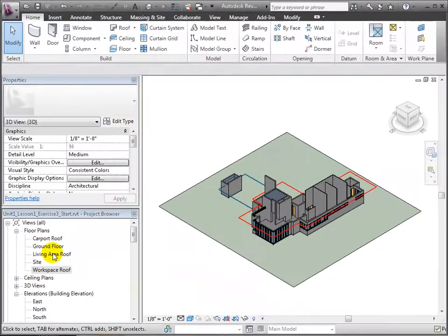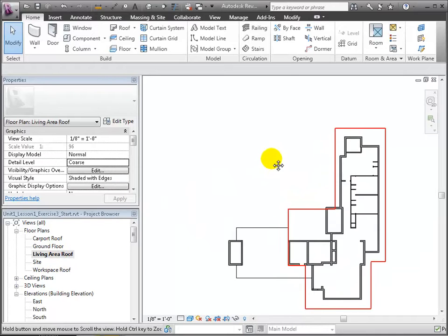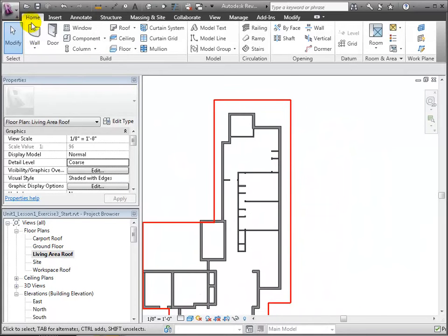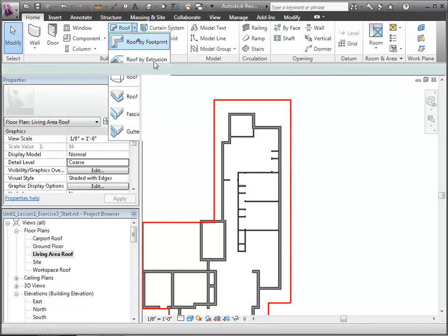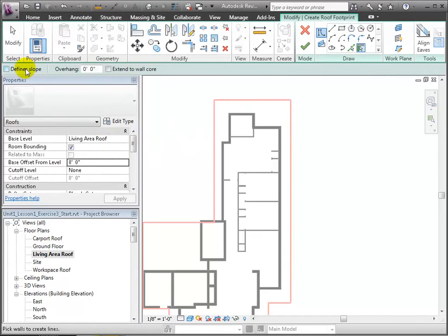Now let's try doing the same, except to make a sloped roof. We will place a partial roof over this north wing of the building. We've already set this example up with model lines at the precise locations of the roof boundaries to make it very easy. We'll leave the slope-defining property checked for the 3 boundary lines here that coincide with the building's exterior walls. Let's use the Pick Lines tool and follow these lines.